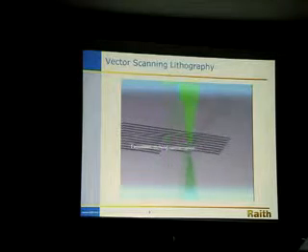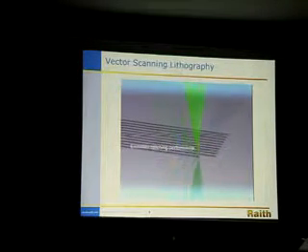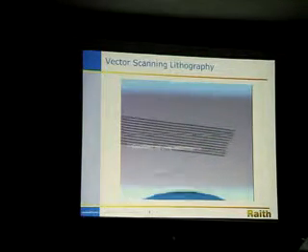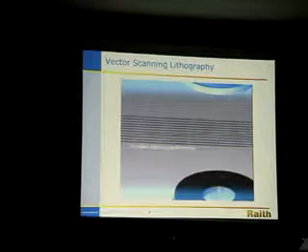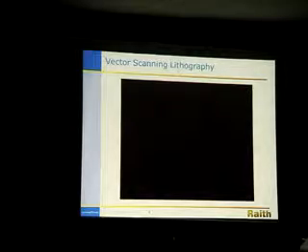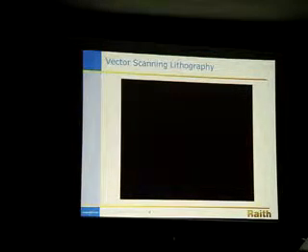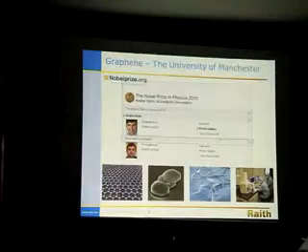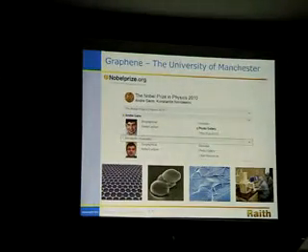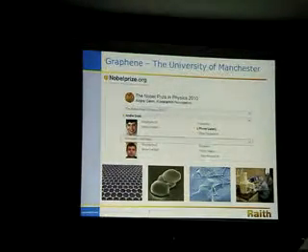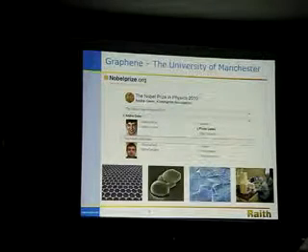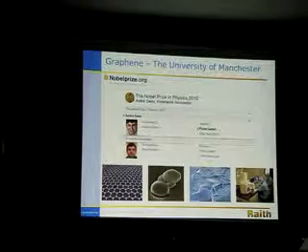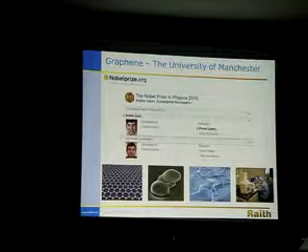And so careful beam control working together with stage positioning allows for stitching together of very large nanoscale patterns over large areas. And so, again, our systems are not really serving manufacturing, because writing with Gaussian beams is a very slow process. However, it's very flexible.